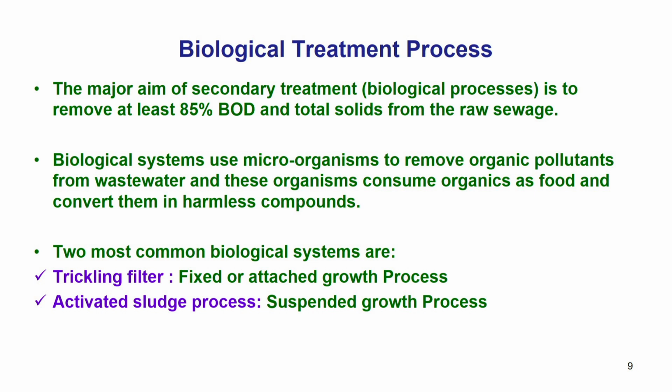In addition to these, we have MBBR, the moving bed bioreactors, as well as MBR, the membrane bioreactors. Several processes have been developed in recent times which can also be used in sewage treatment plants. But these two, the trickling filter and the activated sludge process, are the most common and very old treatment systems, which you will still find in several STPs.